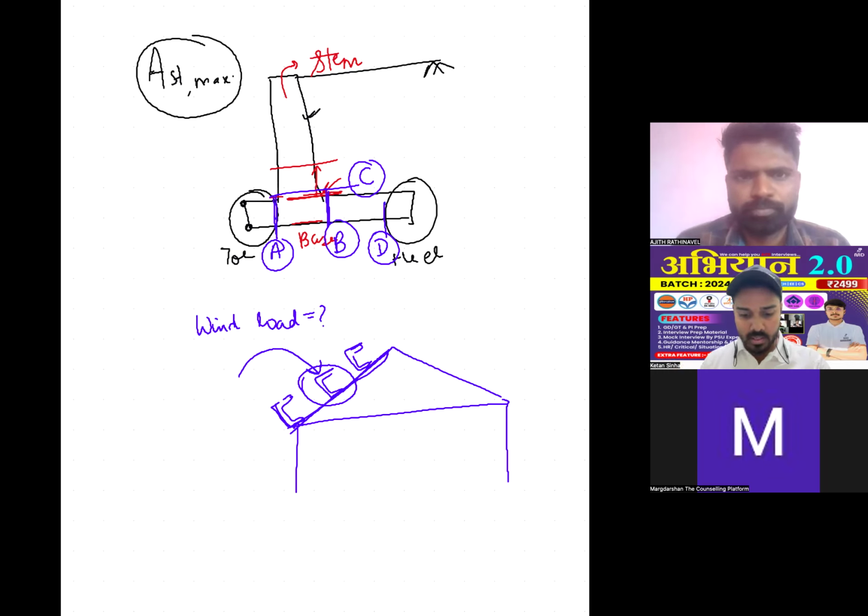On the Mohr circle, you told it well, but do not say that a circle cannot be plotted. Whether it is a point, it is a circle of zero radius. That's the point. Sir, the last point I didn't get. The Mohr circle point: what you told was that we cannot plot a Mohr circle. No, that is not the case. You are plotting a Mohr circle. It is a circle of zero radius, that is a point. Simply tell it is a point. You should not say that we cannot plot a Mohr circle for this.